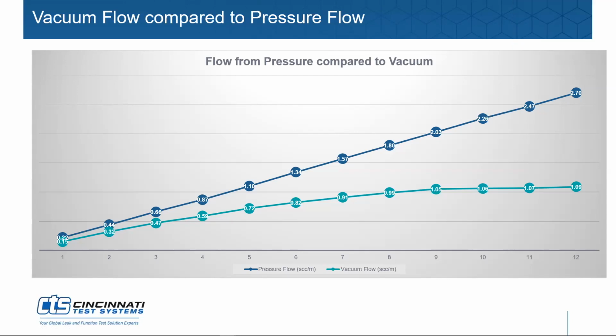And what we also find as you increase vacuum, getting to around 5 to 8, maybe as high as 10 psiv, is that the flow rate actually stabilizes or goes sonic and will remain constant. As much vacuum as you pull on it, you're not going to pull more, faster air out of it. It's going to remain that same flow rate. So it doesn't help you to increase vacuum for flow. It only is stressing your part more.